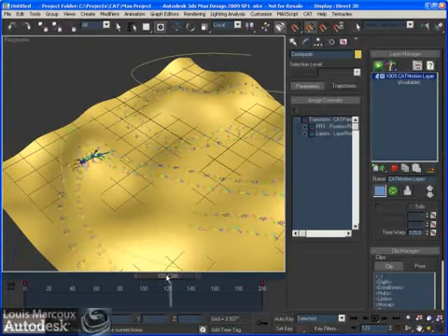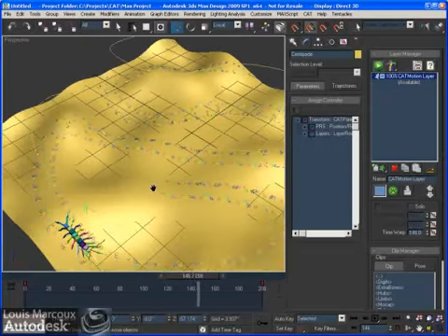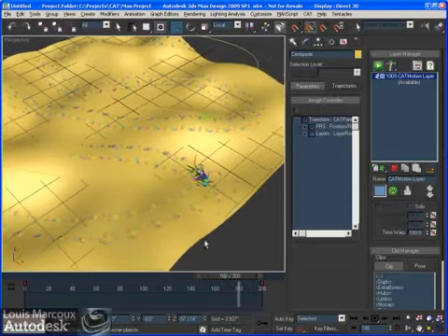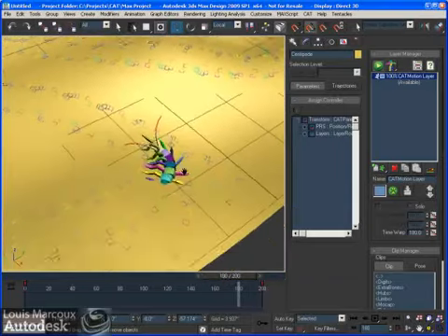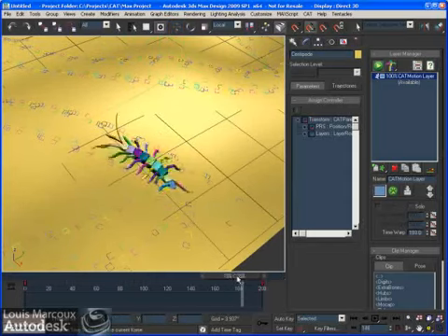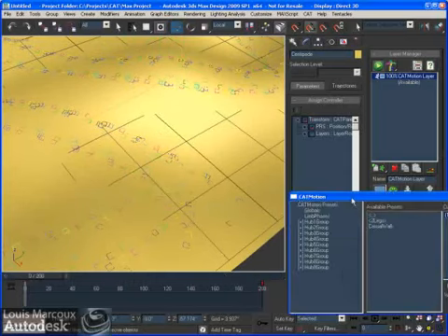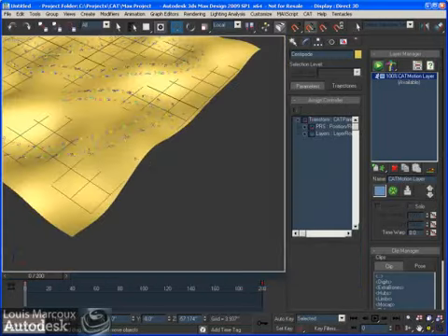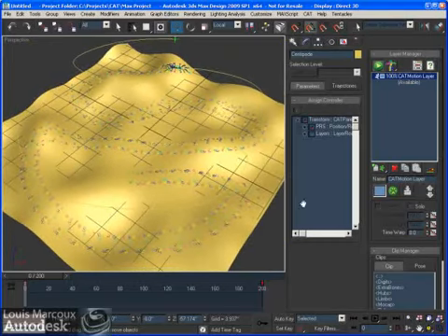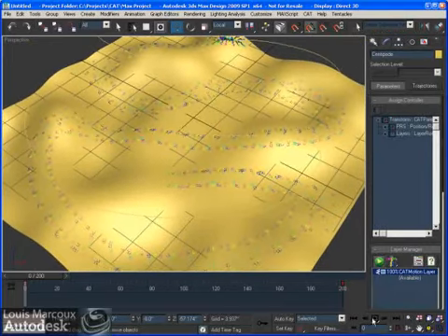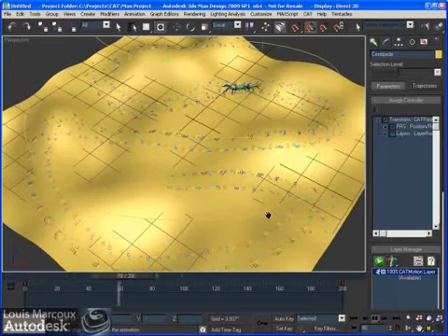So even if you get those areas there, the insect is curving on itself like it should be doing, especially in areas like this. You'll see that the actual centipede is turning on itself to follow the motion like that. So it's Preserve Character Shape again. Go here into the globals. At the bottom here it says Preserve Character Shape, so just make it 0, and if you've got a quadruped or a centipede or things like that, you'll be able to do this. So I'm just going to move that to the side and play the final animation of this guy just going around and following.